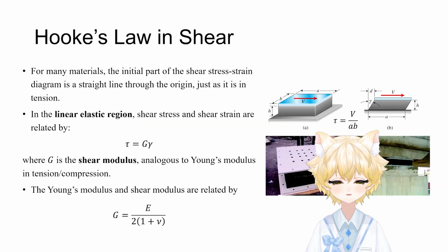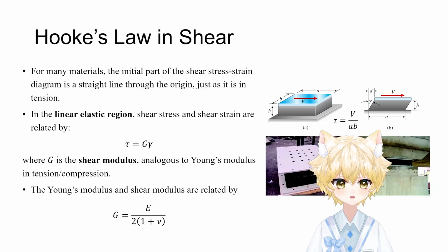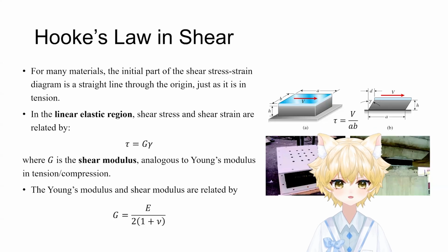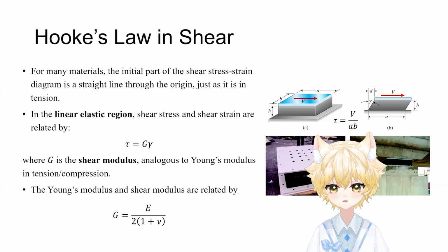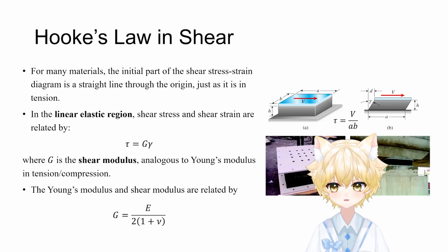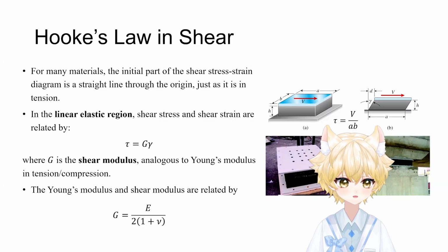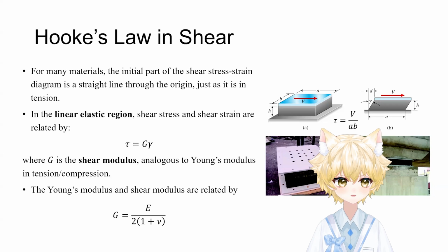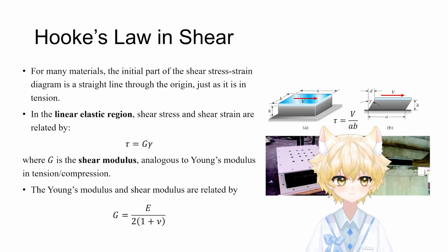It can be calculated using Young's modulus and Poisson's ratio. The derivation of this relationship belongs in a more advanced mechanics course, so for now, I just want you to memorize this formula or add it to your equation sheet. You will need it for future calculations. G equals Young's modulus E over 2 times 1 plus Poisson's ratio mu.